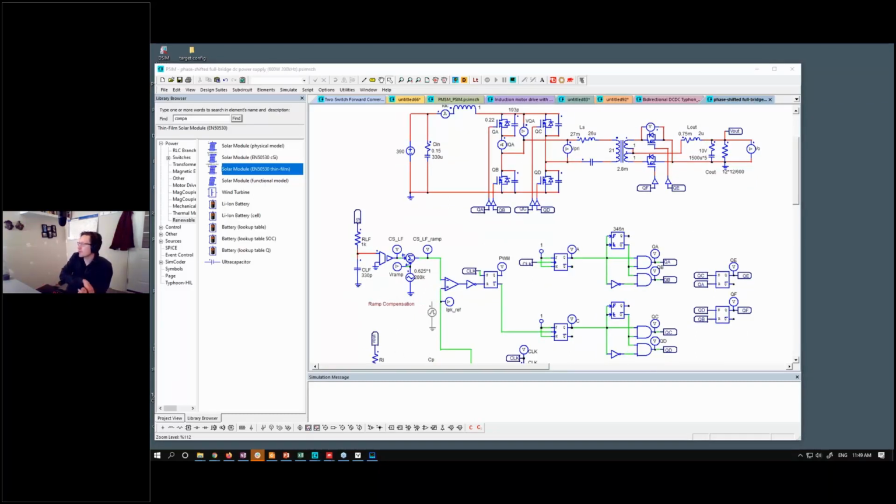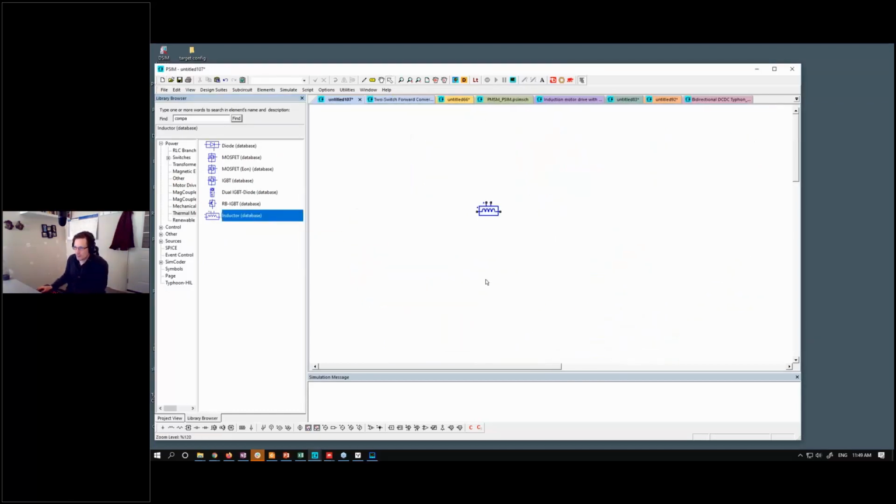No, there's not a transformer-based thermal model in PSIM to compute losses that way. In the thermal module, there is an inductor, and you could use that as the magnetizing inductance. But when it comes to losses in magnetics, the Ridley Works design tool has core and winding loss and proximity loss models, which can be exported into PSIM.